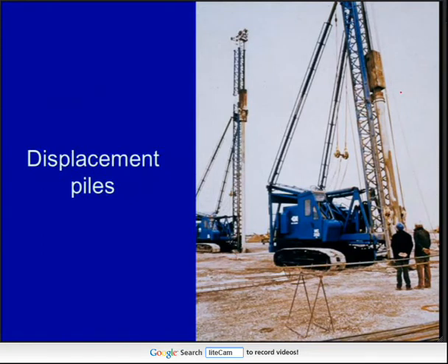But, okay, so we've got a soil which will mobilise a peak strength and then soften down to a constant volume strength. But that peak strength is associated with the grains having to ride up over one another in order to shear. If we have a relatively smooth surface, we're unlikely to mobilise the entire peak strength. And we might want to design with a reduced value of the peak strength, possibly even the constant volume strength, to avoid over-designing.